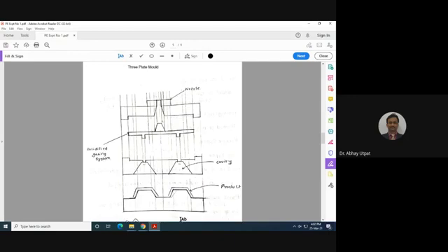Now this classification is as per the number of plates. Now here you are observing 2 cavities. This is the first cavity, this is the second cavity. There may be 1 cavity, there may be 2 cavities, there may be 3, 5, 10, 20. So single cavity mold and multi-cavity mold is the second classification. I repeat once again.